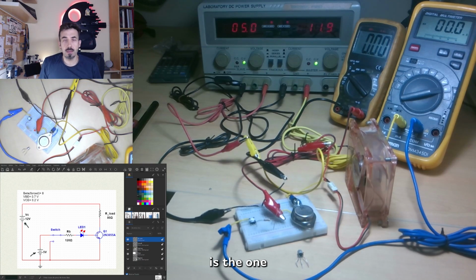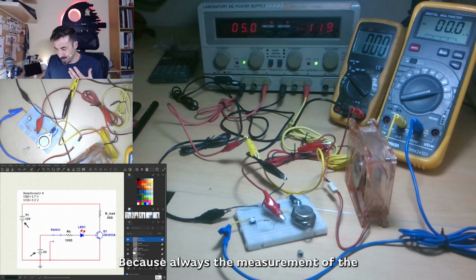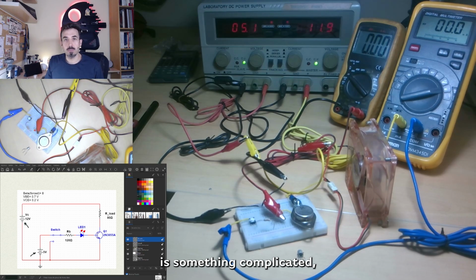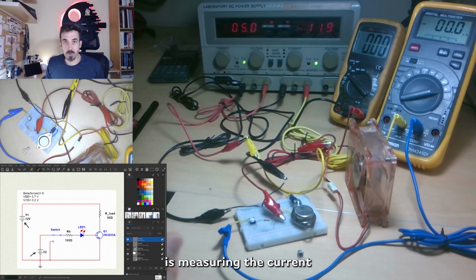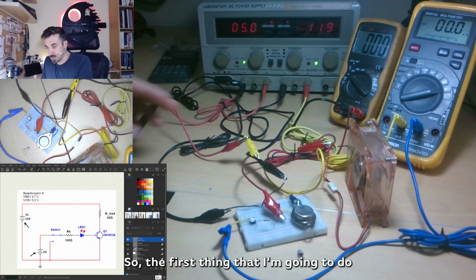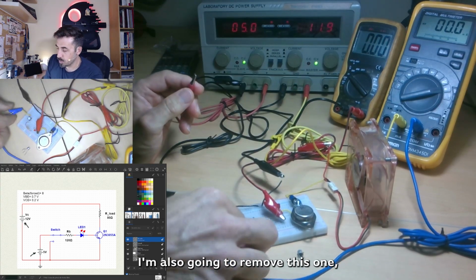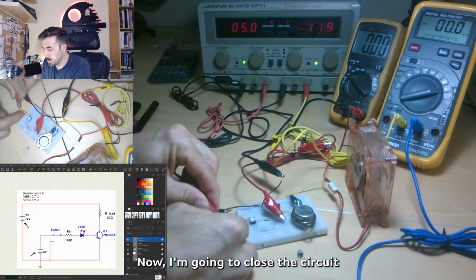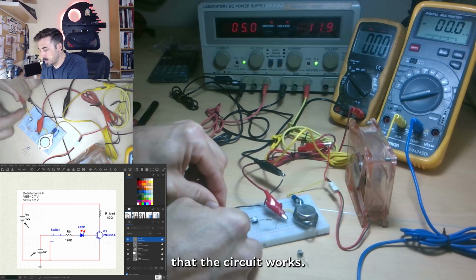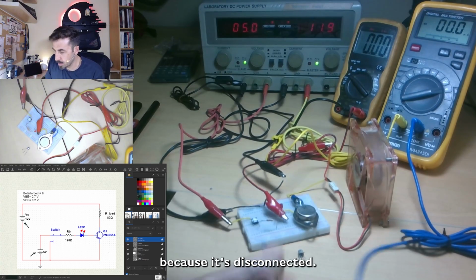Another interesting measurement is the current through the collector and also the voltage at the collector. Because measuring current in the laboratory is always something complicated, I'm going to do it here on the spot. My ammeter right now is measuring the current through the base. So the first thing I'm going to do is identify the 5 volt and remove it, and I'm also going to remove the two terminals of the ammeter. Now I'm going to close the circuit and verify that it works. If I press here, everything works. Of course, I don't have current because it's disconnected.